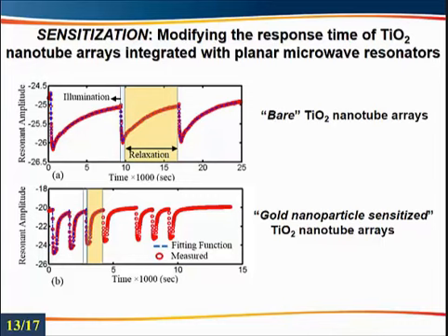The other interesting thing we've observed is that when the gold nanoparticles are of the right size, you can use the plasmon resonance and also get sensitization to green light, which is 532 nanometer light. We've since also worked with quantum dots and observed the ability to sensitize over a wide spectrum, over a broadband. So we are talking about broadband light detection, not just UV photodetection, tunable across the spectrum, and yet preserving very low levels of detection.